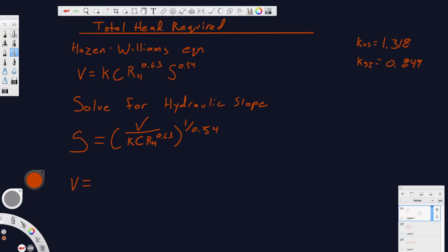So one thing we need to do is solve for velocity, right? Because we're not explicitly given the velocity, but we are given the volumetric flow rate. And this is something that hopefully you're going to be able to just know off the top of your head. There's probably the equation in the reference material, but the continuity equation is something that's going to come up so often that really if there's one equation you should know off the top of your head, this is going to be it.